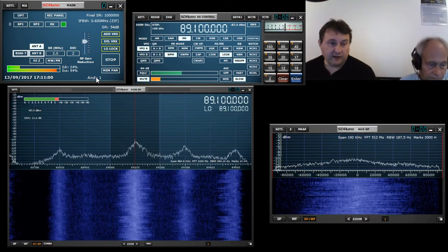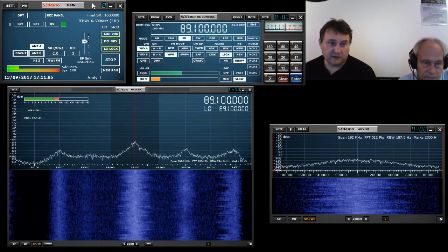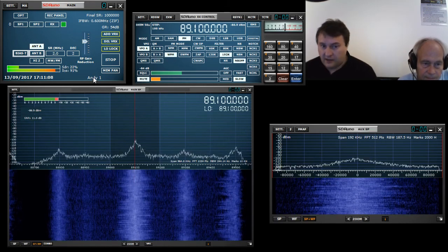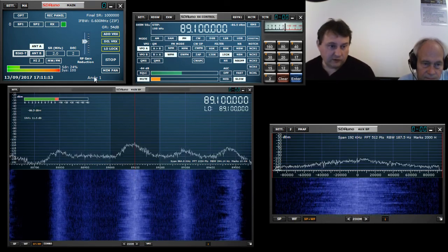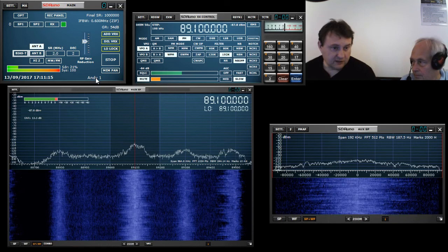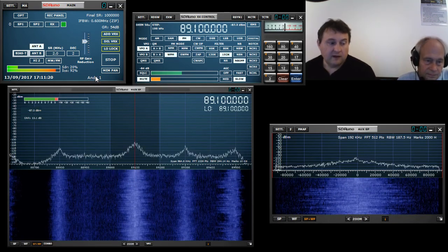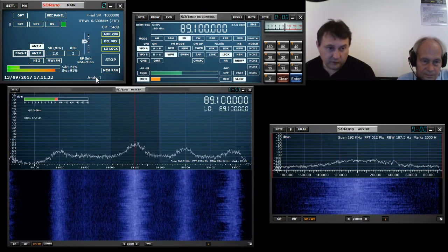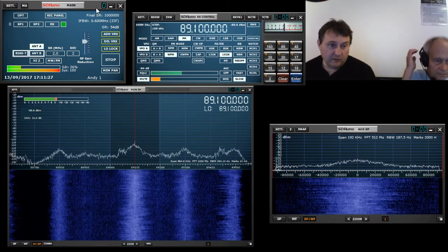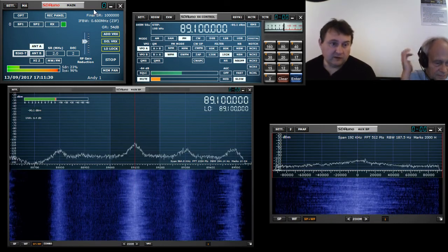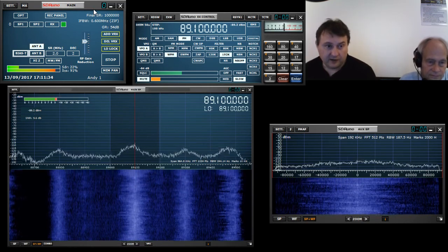If I left click on this, although you can't see it, the default workspace has now been renamed to Andy1. The way to store this is slightly convoluted, and we are going to address this in probably the next release. You hold down the left control button, then click on the words where the workspace is with the left mouse button. The menu will appear, and then you can select the workspace in which you want to store it. So I'm going to left click Andy1.